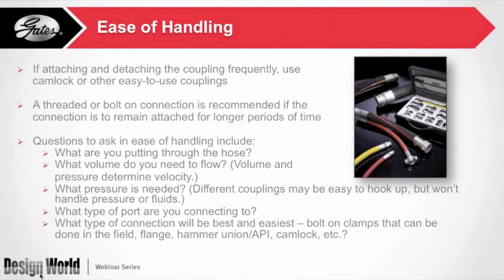Pick the appropriate coupling that's going to meet the pressure and the requirements for the job that you've got. And then you're going to make sure that the threaded or bolted connection is recommended if the connection is to remain attached for longer periods of time. So for instance, if you've got something that's going to be hooked up to a water pump over a period of a month or so as you're pumping water out of a dredge or something like that, then you're going to want to bolt that on so that it's not going to come loose when someone's not watching it.